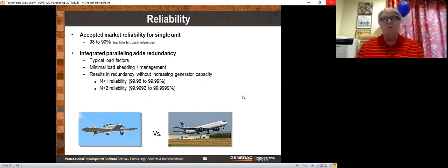Well, we didn't underprice it. 4 500 kilowatt generators is significantly less expensive than a 2 megawatt. It's easier to install. It's easier to maintain. It is easier to get parts for. It's easier to troubleshoot. And it turns out that with those, the actual load on the plant when we had our first outage was about 900 kilowatts.